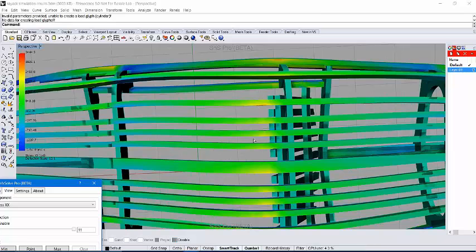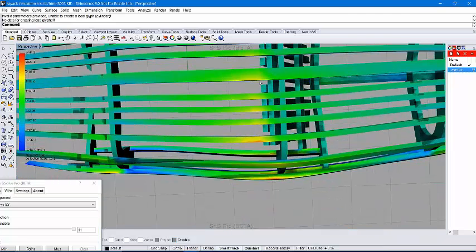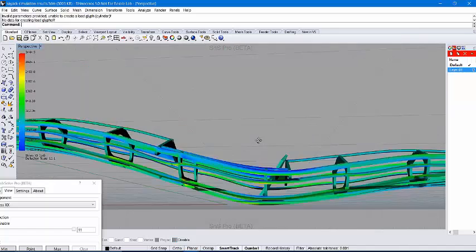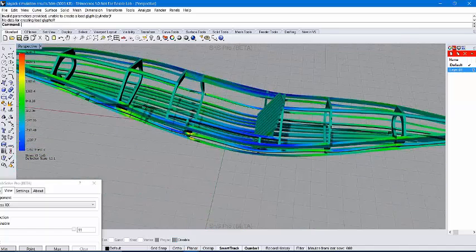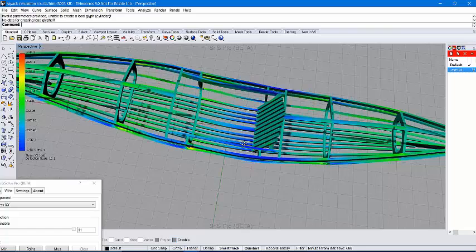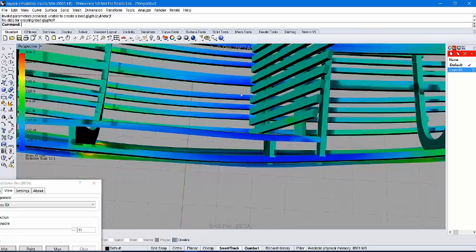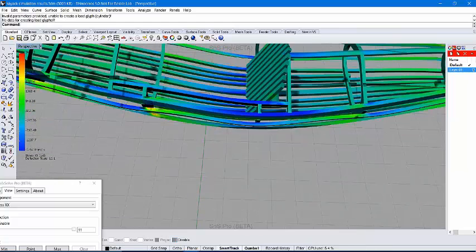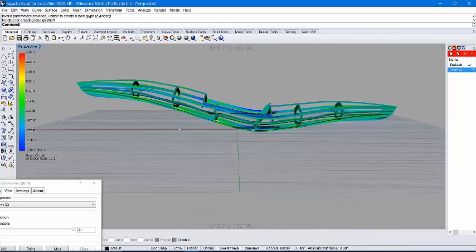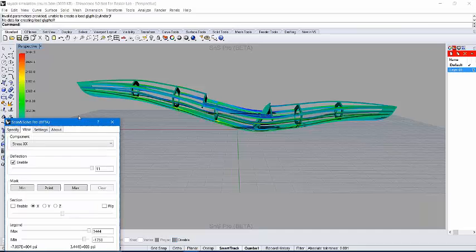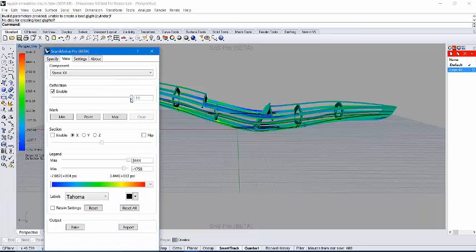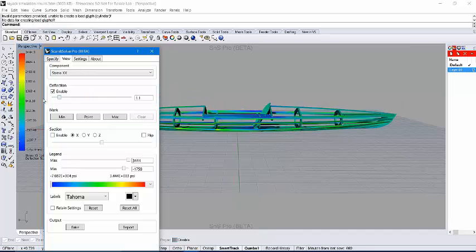And if we look at the top, this is kind of being pushed together. So we'd expect to see compression, which is what we do in the areas of bending. We see darker blues, all negative numbers representing compression. So this is pretty useful when building to know where your material will be in compression and tension. If you're dealing with brittle materials, you know it's more likely to break in tension, so you've got to be aware of that. So this mostly sums up the viewing page, what I wanted to go through.